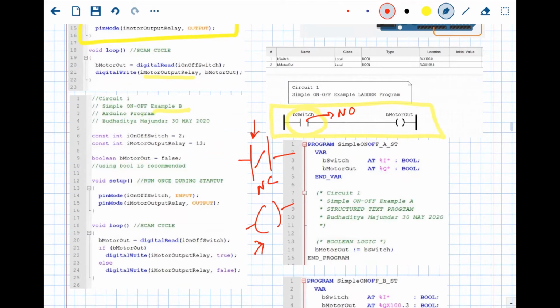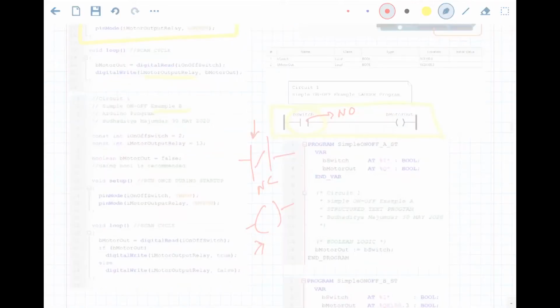State machine in ladder is very difficult, and that is why we are all moving towards structured text. I have done both ladder and structured text, and I have a very hard time writing like a 200-page long ladder program. Again, the writing part is easy. Maintaining a ladder program is the most difficult part.